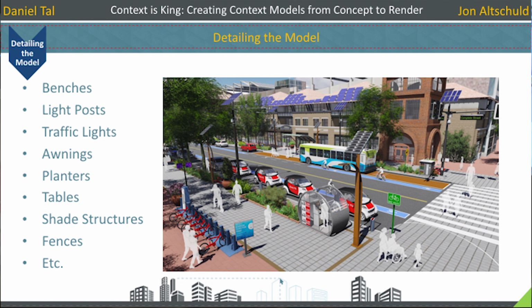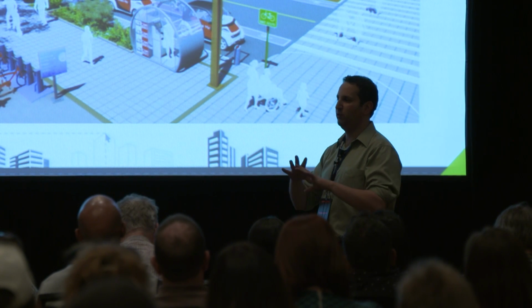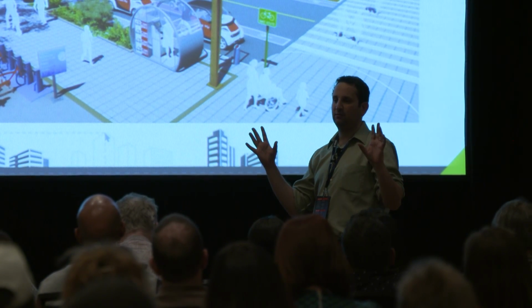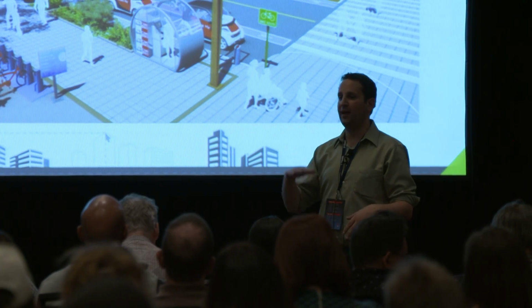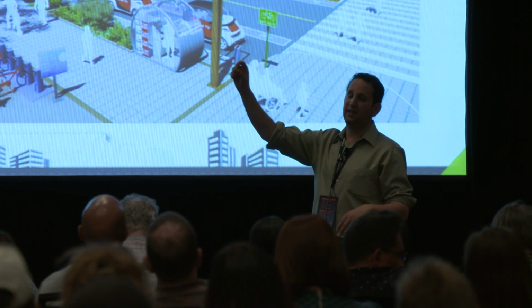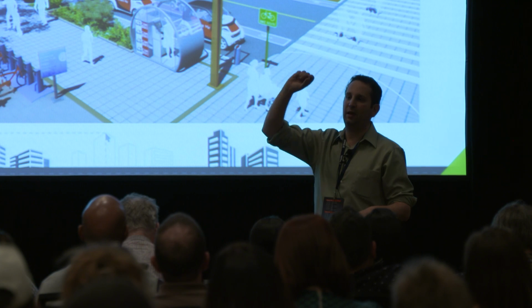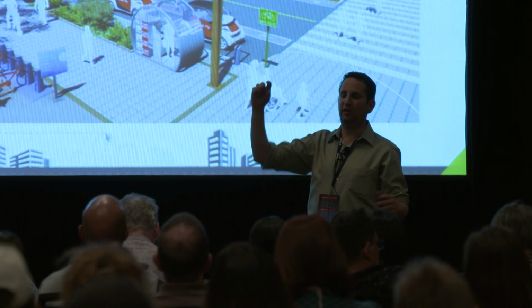Question towards the back? Yeah, so are you adding most of those amenities in with Lumion or with 3D Warehouse? And I ask because I'm wondering how big your file would get. Sure. So what the question was is, are we adding that information in SketchUp or in Lumion? How big are our file sizes? To address file size, number one is because we're bringing high resolution aerials into SketchUp, and there's a setting in SketchUp, and I can show it to you when we demo, to make sure that it does display a high resolution aerial.